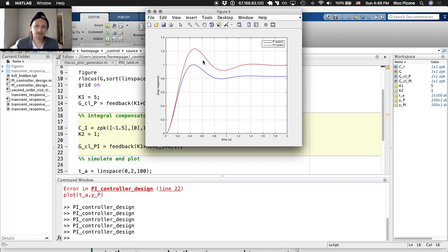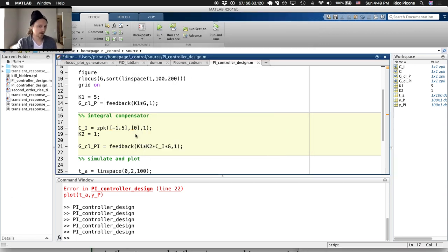There are different ways we could go about it. So let's say we can essentially change 2 things. We can change our gain. So right now I have K2 at 1. We could tweak that a little bit. And if we increase that gain, we would hope to see our transient improve, but we don't know for sure if that's going to happen.